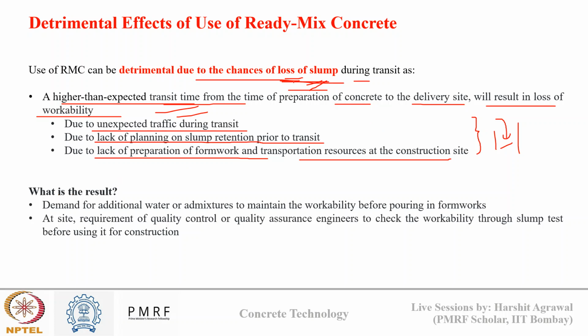So if we are recording loss in slump, then we can demand additional water and admixture to maintain the workability before pouring, or at site we require some quality control engineers to check the workability using slump test before it is used for construction. So these are the precautions that we need to take within ready mix concrete.